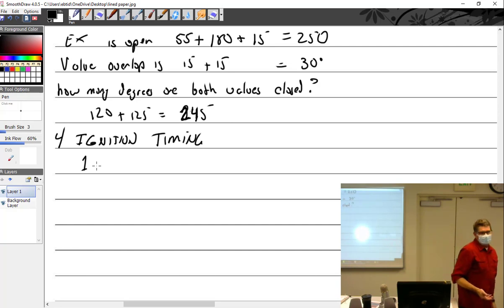Well, if you try and start an engine and you don't have the spark at top dead center or somewhere behind it, when the piston's coming up on that starter and you ignite it, it does turn around and go the other way, except it doesn't do that gently. It explodes the starter Bendix, the starter ring gear, and it destroys your engine.